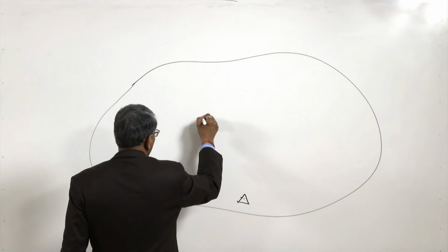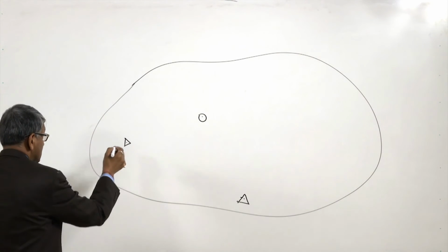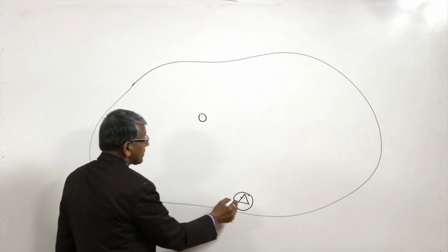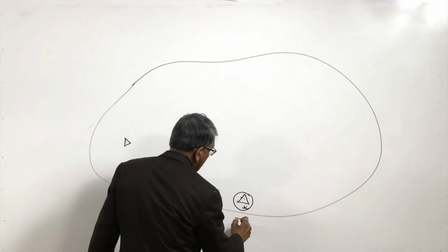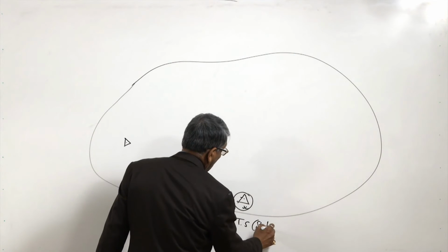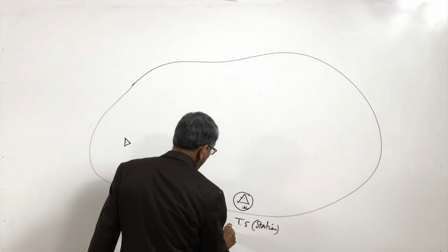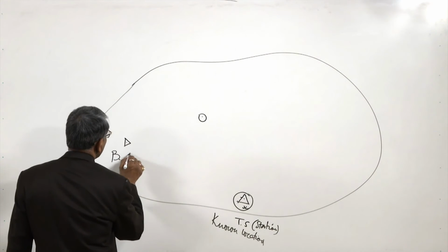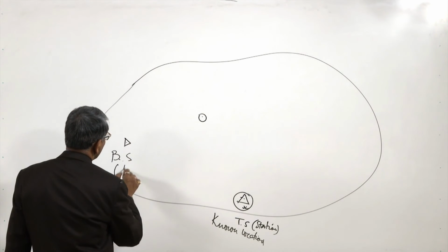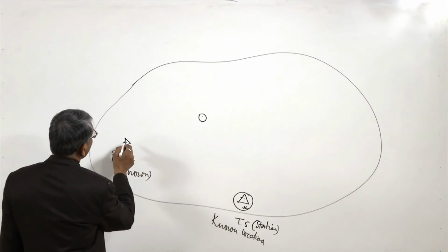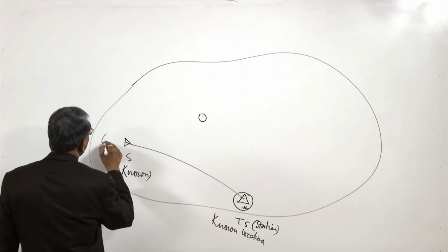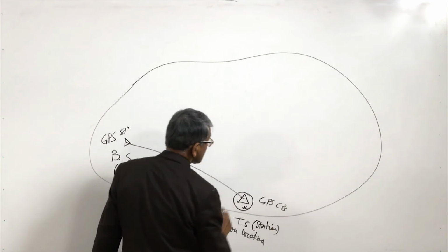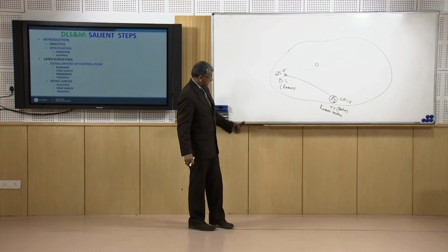So by setting up our instrument, first we will set up our instrument on one of the control points, and we will give the coordinate to the total station, TS as station, known point, known location, and we will take the backsight to this, and that is also a known location. So from this to the known location, these both are GPS stations or GPS control points you can say. So this is the thing we will start with.